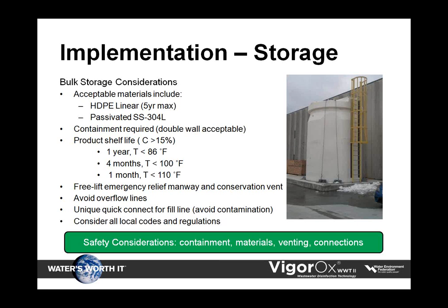Please note that in addition to temperature, the rate of loss of PAA in storage is a function of two things: the purity of the raw materials used by the manufacturer and the process by which PAA was produced. It is important to understand this because two PAA solutions of the exact same formulation may have very different shelf lives.